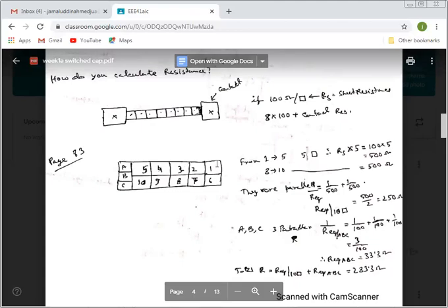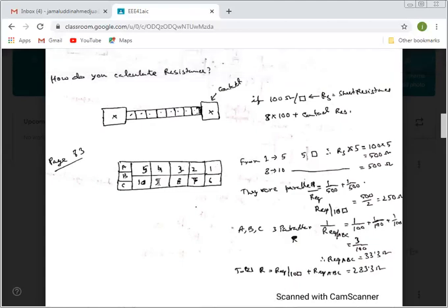So I have another resistance like this. So we divide it into squares like this. Here is 1, 2, 3, 4, 5, 6, 7, 8, 9, 10, ten of them like this. And then we have a non-regular square here. So we break this part into several new squares: A, B, C, another new square.